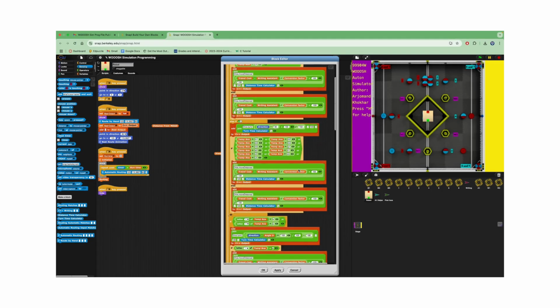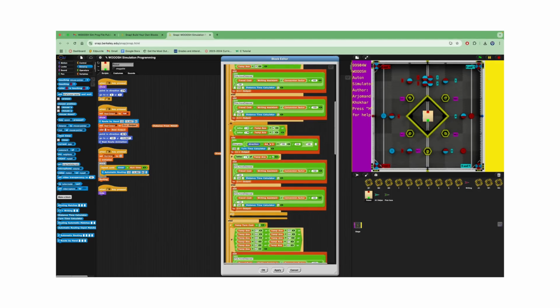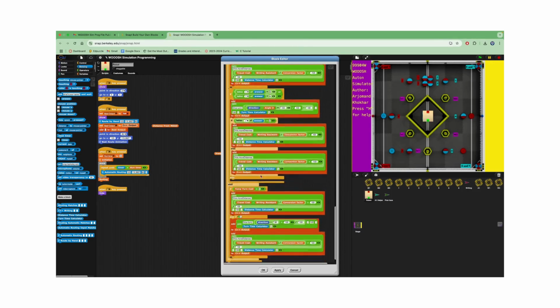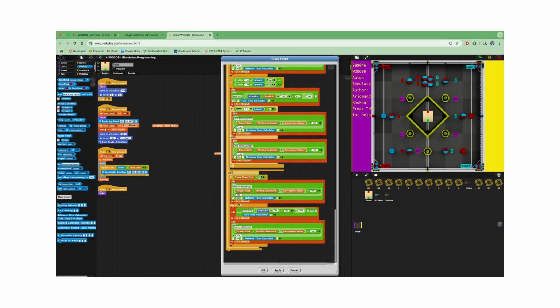And for turning, it is down here. It will be absolute turning. So if you're starting at 0, it'll go through and say, like, -470 if you're turning to the left 470 degrees. And all of the mobile goals have different things because they have to ensure that they are on the correct faces. That shouldn't be something you have to mess with, just changing the characters here.